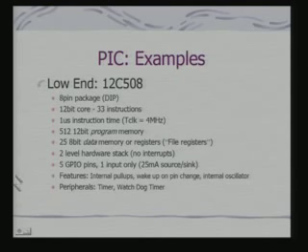So, it has only 512 words of 12-bit program memory. It operates at 4 megahertz. It does not have 35 instructions, but 33 instructions. It is typically an 8-pin package. It has 5 GPIO pins and, interestingly, only a 2 level hardware stack, and no interrupts. And its peripherals are simply a timer and a watchdog timer. The watchdog timer is there to recover, and the timer is for a simple application. So, for a very simple application, you can use this PIC.